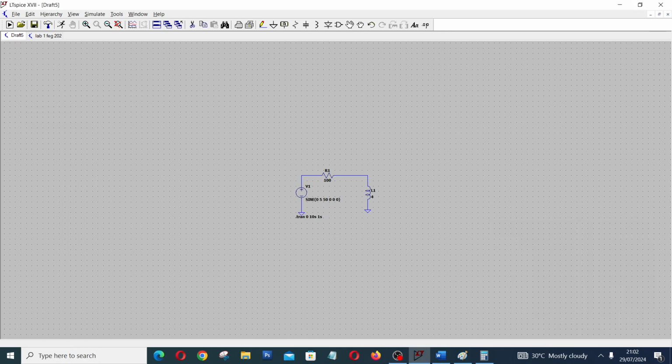Well, good evening, everyone. In this experiment, I want to quickly show how power factor can be corrected using a static capacitor to compensate for the lagging power factor. Like we have already known, lagging power factor happens due to the presence of inductive load. When your load is inductive, it tends to draw excess reactive current from the system.